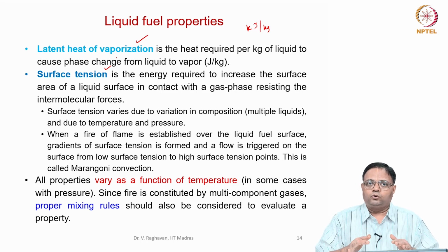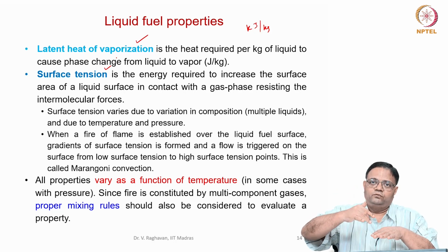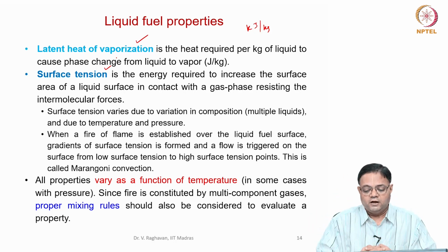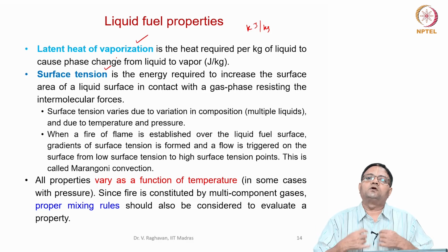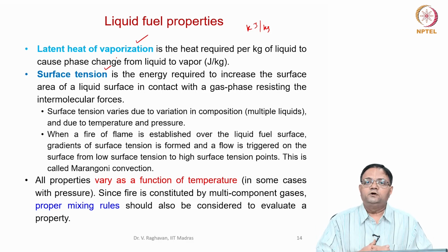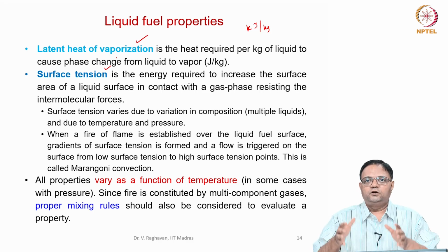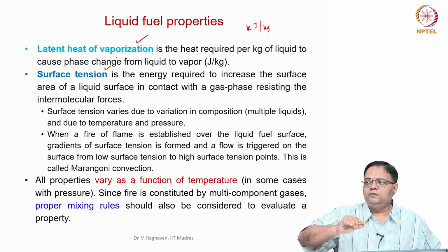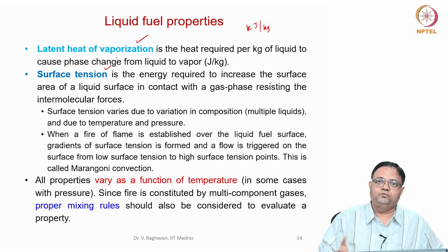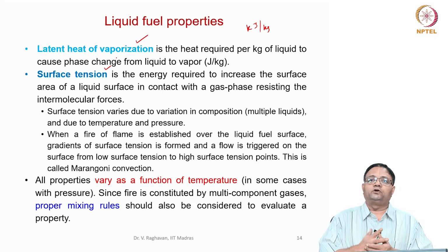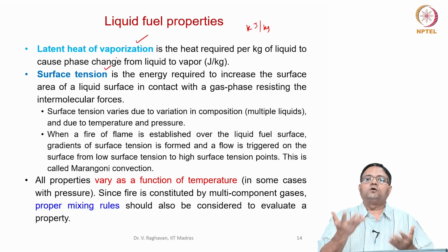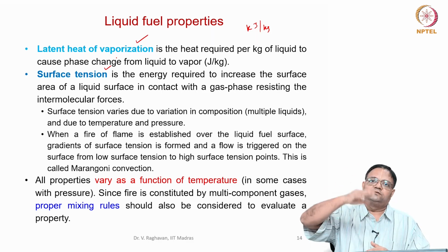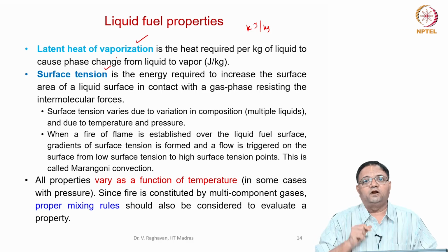So, when you want to have some surface interaction with the vapor phase, liquid surface and vapor phase interaction, then the liquid has to overcome the intermolecular forces. See, a simple test is to put a capillary tube in a beaker of liquid. How the liquid rises in the capillary tube depends upon the surface tension, one important property. Okay. So, the cohesive forces, the intermolecular forces, what we call, should be overcome by the surface tension so that the liquid rises. So, that is a surface phenomenon basically.